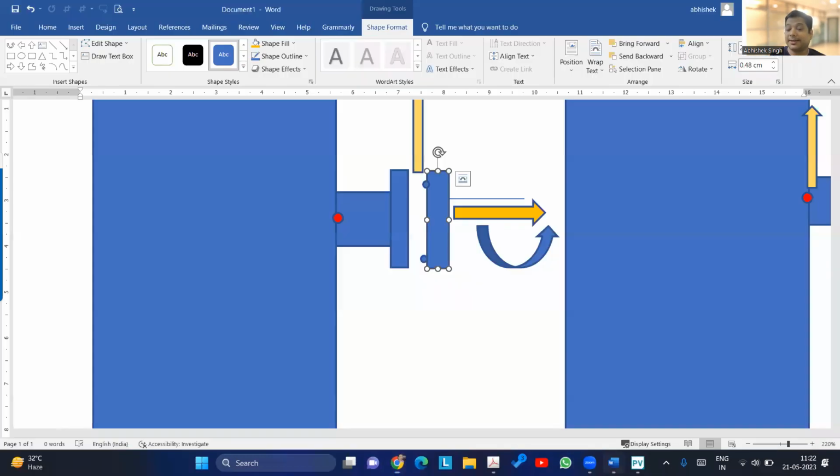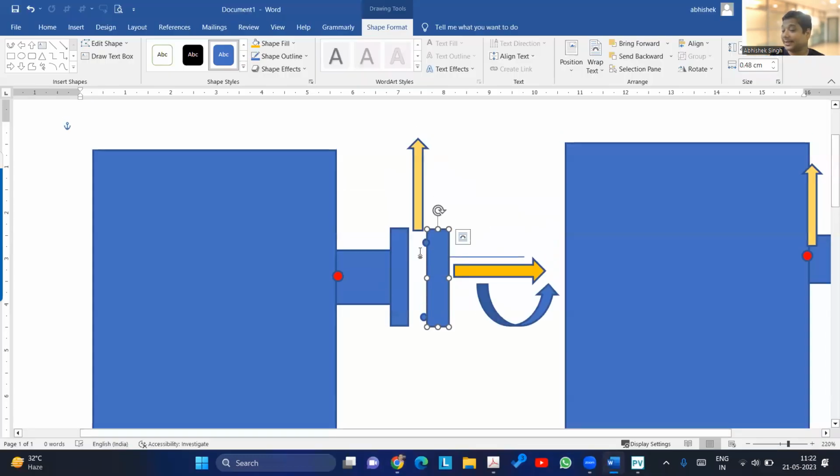Still we have covered only the second part. First, we saw the WRC calculation where we analyzed the junction. Second, the derating of this flange. Third, even the nozzle neck also needs to be qualified, right? This also you can do, Uday.